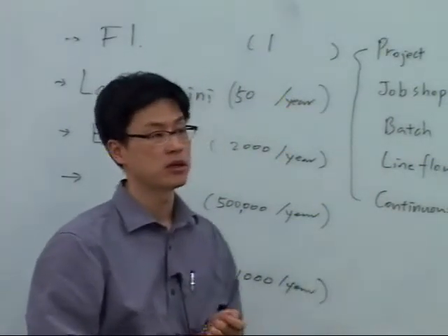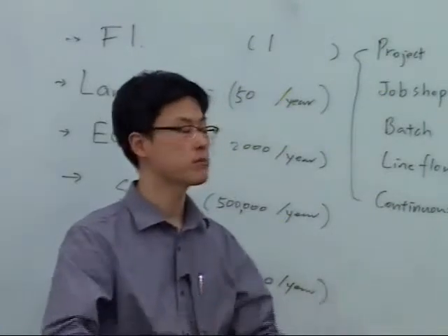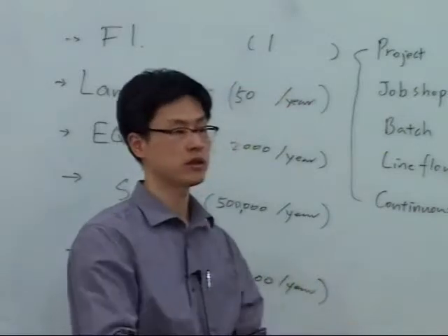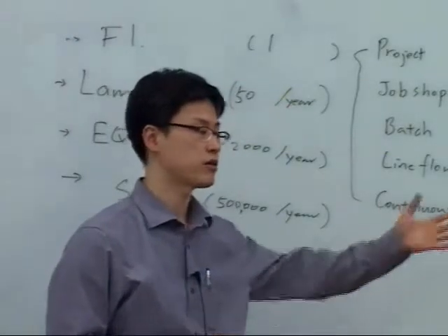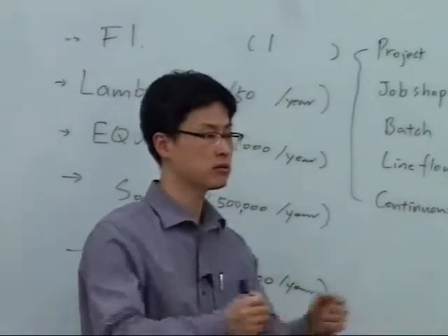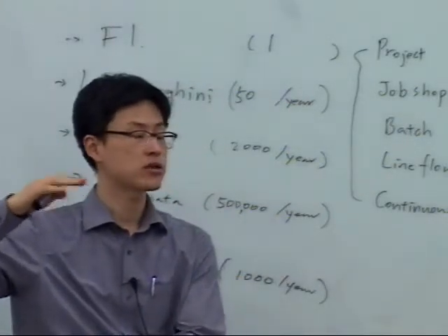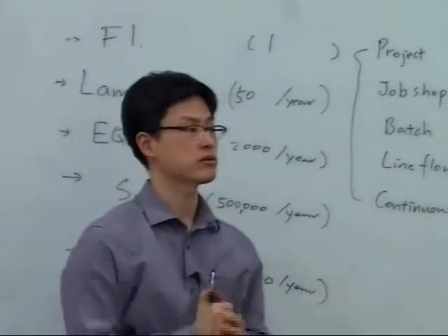For example, in front of the door panel stamping station, you don't just stamp one thing and deliver it to the next workstation. You get tens or 20 or 30 door panels, stamp and stack them, and once this batch rack is filled, you move that batch rack to the next workstation.